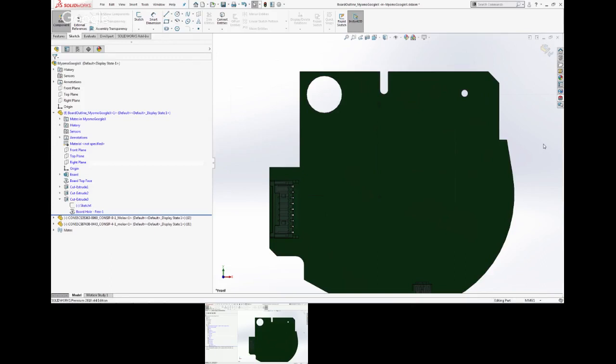Yes. And two things that I want to say about keep outs. For the electrical, they know that we have a keep out and a placement barrier. So what we have in 2018 is a component placement barrier that you can define on X, Y, and Z. So for height restriction and then also on the XY plane, or how far it is from the board edge or how far from the enclosure. You can define this in SolidWorks Mechanical with an envelope, and 2018 allows you to push non-electrical models, so solid models that represent these barriers, heat sink, or enclosure over to the electrical side seamlessly without having to import a step file. So that's what we support.